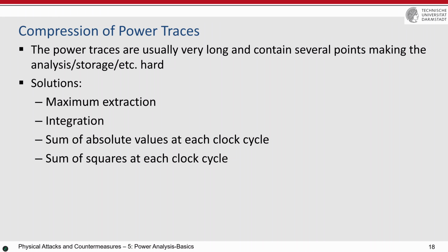It takes some time. Then many years ago, there were some discussions on how we can compress this data, the power consumption traces, because as I explained, the power consumption values are already low pass filtered. And usually the peak of the power consumption of every clock is important. It means that if you just do the peak extraction, or maximum extraction, then you should still be able to run the attack.